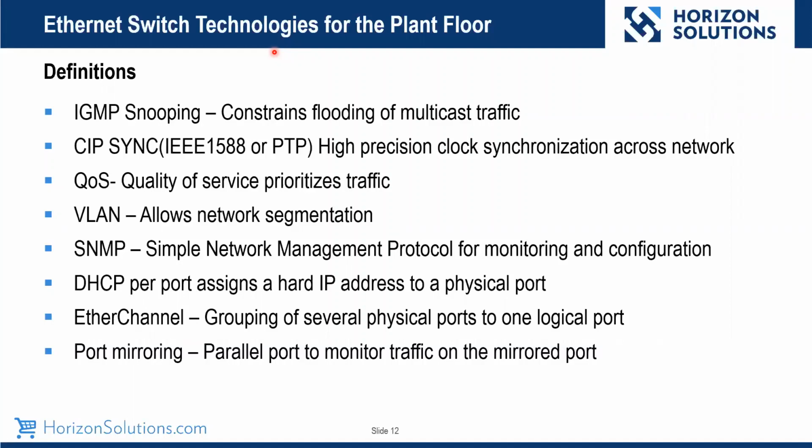Port mirroring is the ability to mirror traffic from one port to another. So say you have some issues and you're talking to that drive and it keeps getting yellow triangles and timing out. So how do you find out what's going on? You can mirror that traffic to an open port, and then you can use something like Wireshark to record that information, and then you can analyze it. Either you can analyze it yourself if you know what the traffic looks like, or you could send it to Rockwell Automation tech support, and they have the skill set to look at that and help you analyze issues with your network.